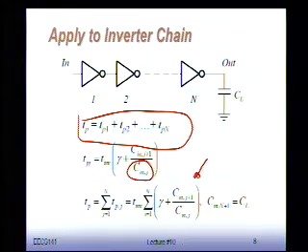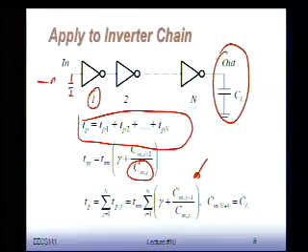There's two extra constraints we have. We say that the input capacitance has to be a certain value. Let's say I'm going to make, for instance, the first inverter minimum size. Because I want to make sure that the load on the previous stage is fixed. Okay? Anything that sits in front of here should see a fixed load. So we make this size 1. Whatever size 1 means, but this could be, for instance, a minimum size inverter. So we know the input capacitance Cin of gate number 1. The other thing we know is the load capacitance of the last stage is a given factor.